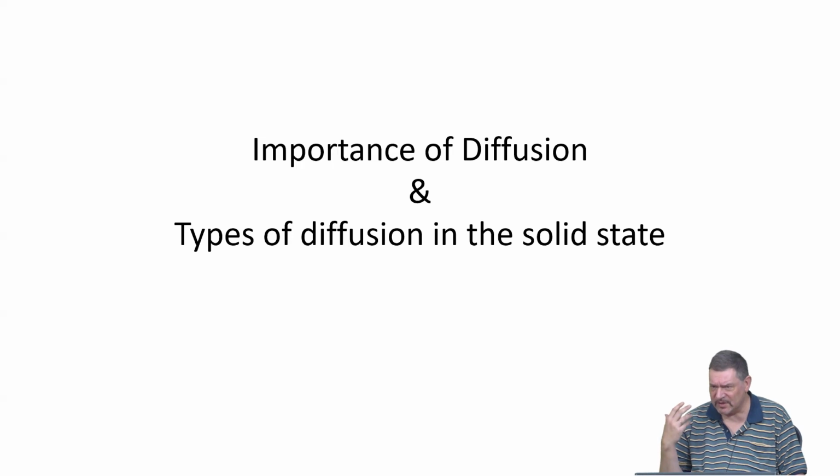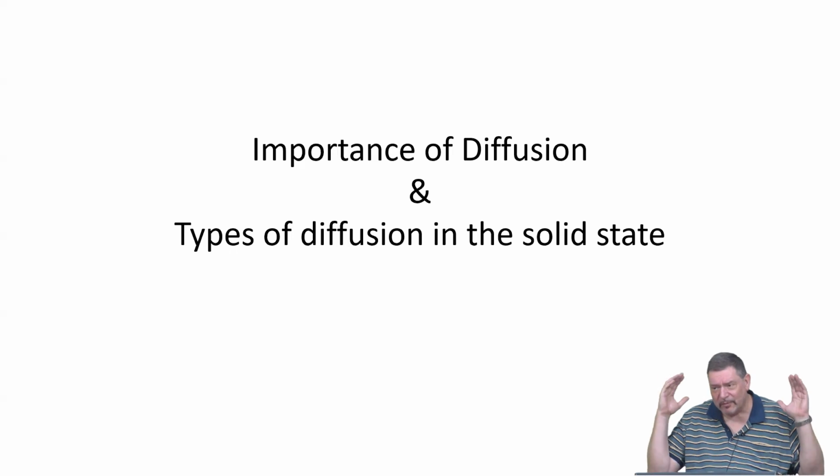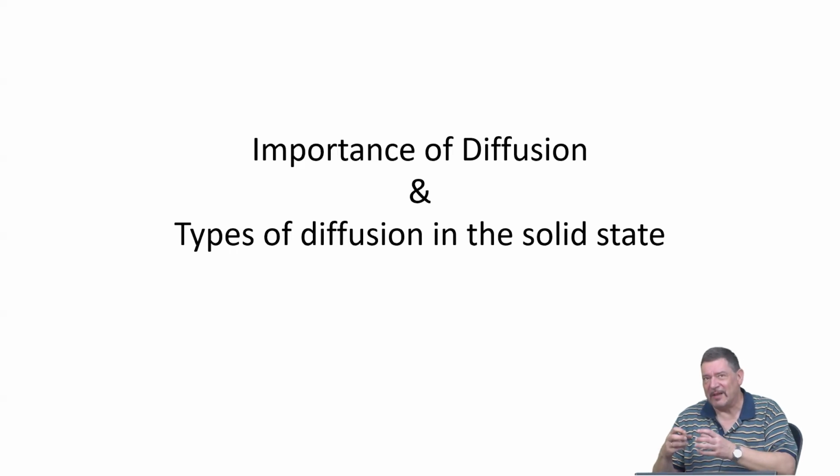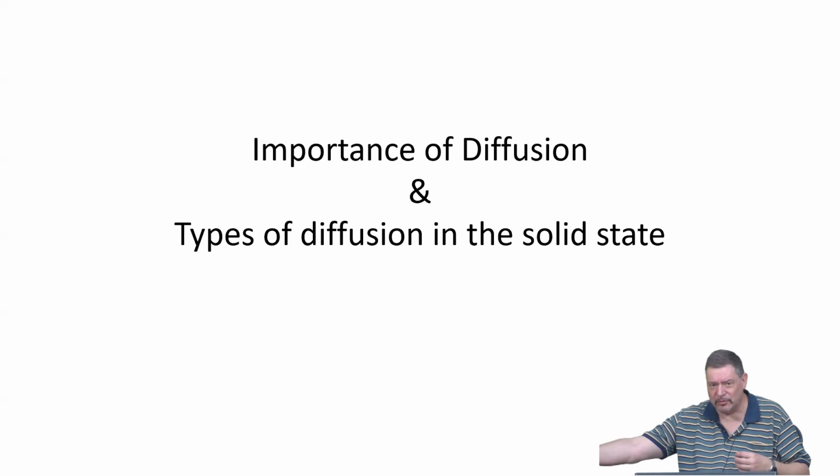But then when we especially think about substitutional diffusion, they often do not differentiate more according to the different types of diffusivities for a uniform homogeneous material, let's say the big single crystal that we would always have in mind as an ideal concept. But then even more importantly, if we think of real materials, also including all the defects that are possible and that we always find, especially in metallic materials. And there also the different diffusivities even have different types of diffusion kinetics.